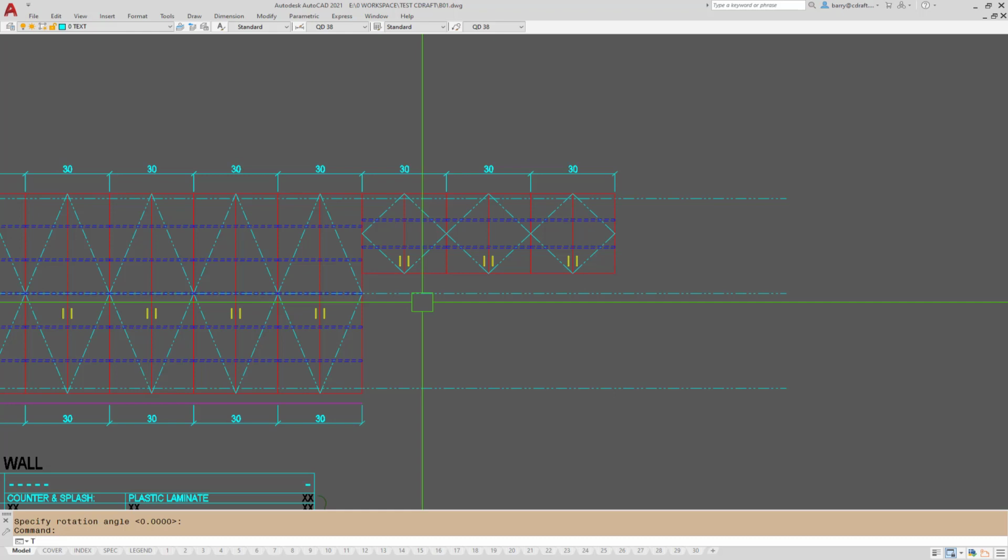Let's do a B12, B12 again. We already have our width, but guess what? When we ran the filler command, it reset the countertop height to 0, so we need to type that in. So let's do 36. Number of shelves is 1. Number of cabinets is 3. We're not going to switch, building from the left to the right, so spacebar. We're going to auto insert, so spacebar again.